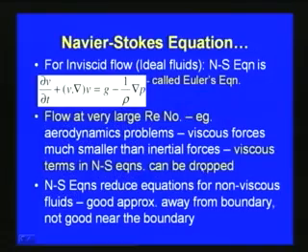So, for potential flow, we have already shown that the viscous terms nu del square u, nu del square v and nu del square w are zeros, and finally the Navier-Stokes equations are transformed into Euler's equations, which we can solve.